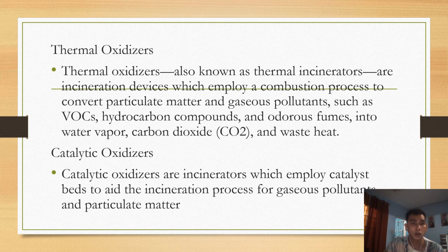Some catalytic oxidizers are not suitable for incinerating gas and emissions containing PM, as the particulates can coat the surface of the catalyst bed, disrupting the oxidation process. Newer catalysts allow catalytic oxidizers to handle most gas and PM compounds. The types of catalytic oxidizers include regenerative catalytic oxidizers or RCO and recuperative catalytic oxidizers.